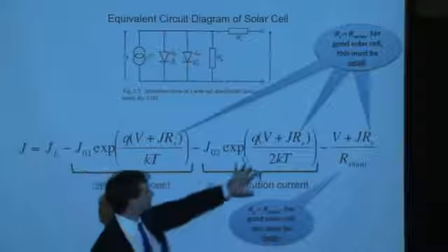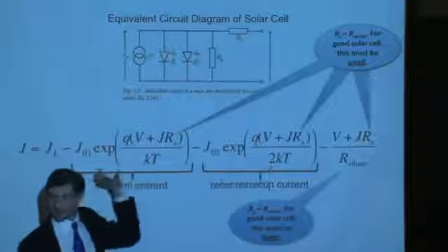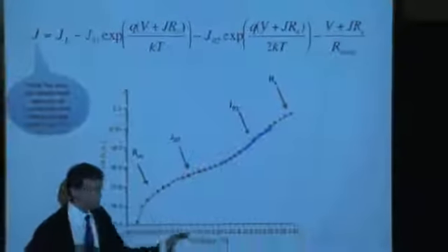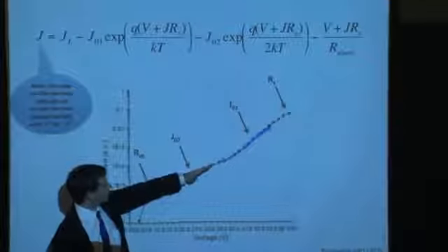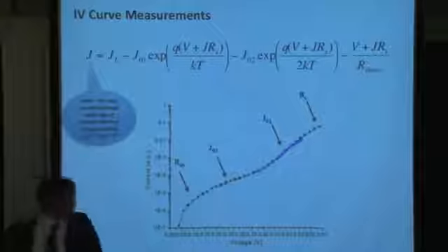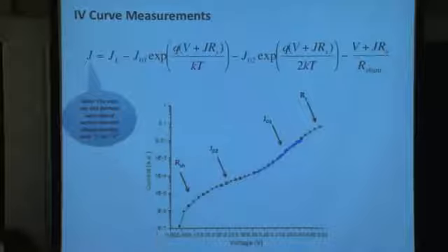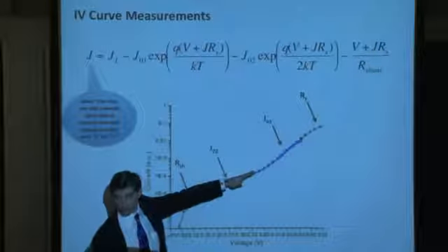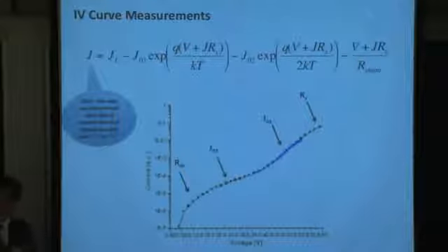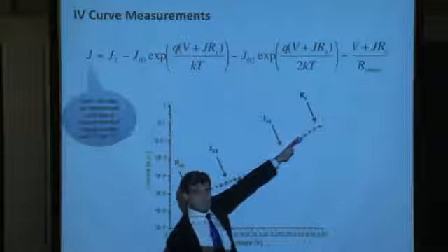And that's why you see, when you plot your IV curve on log linear scale, you see essentially two flat portions on your IV curve. Let me forward that to the next slide right here. Here we go. So this is log of current versus linear voltage. And you see one flat portion right here and another flat portion right here before the series resistance begins to dominate at too high voltage and your shunt resistance dominates at too low voltage. This flat portion right there is being driven by recombination within the space charge region. Why? Well, the forward bias voltage isn't enough to really lower that barrier enough to allow the carriers deep within the bulk to recombine, so the carriers are recombining in the space charge region. Whereas here, they're recombining within the bulk.